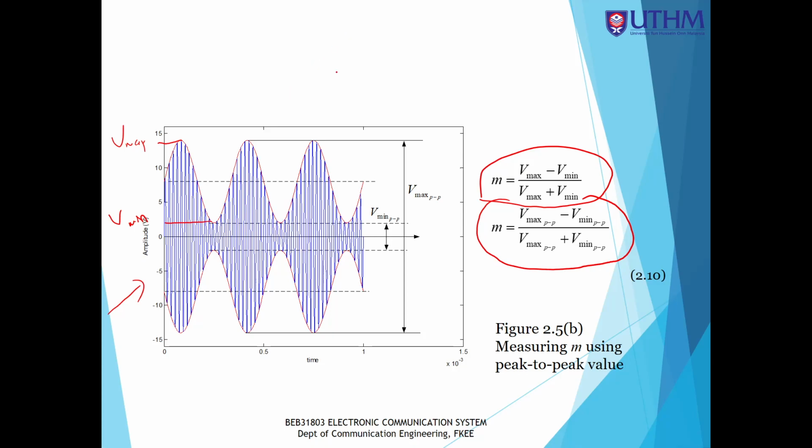From there, students need to find the modulation index, Vm, Vc, and calculate the power and so on. You need to understand that the given values are the maximum and minimum, then you can do the calculation to find the modulation index, power, and so on.